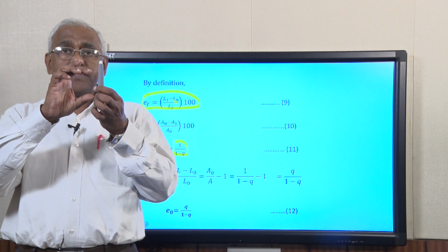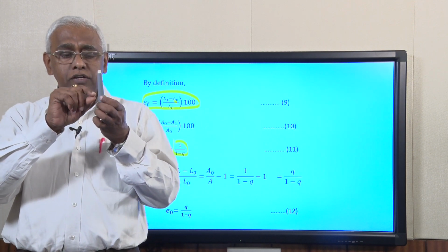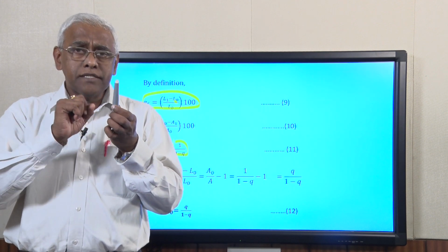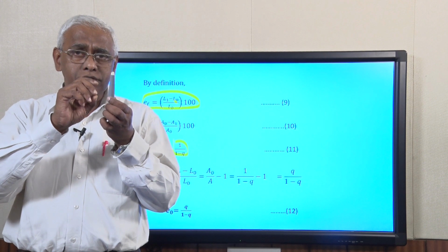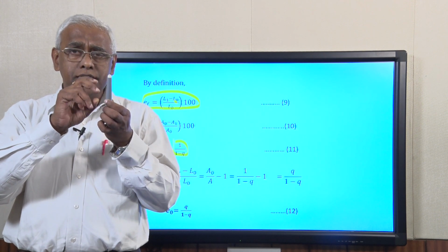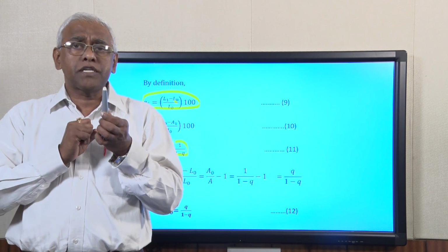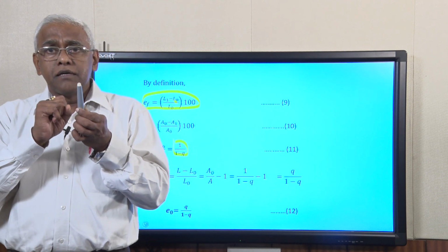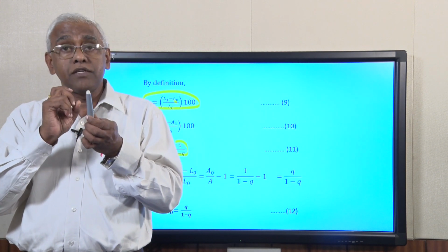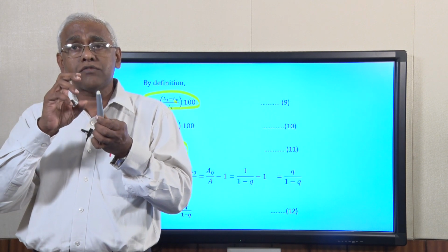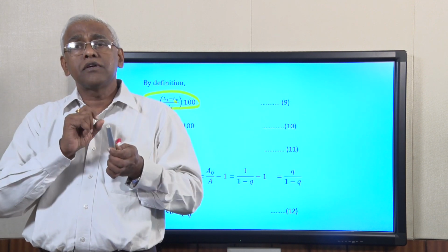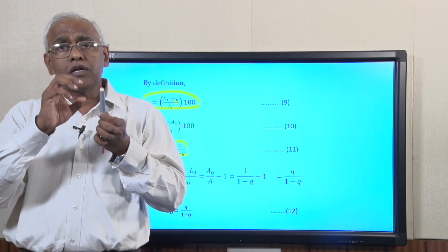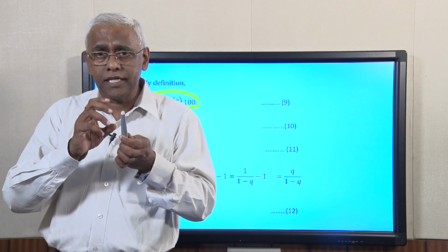Okay. So, when you are keeping a 2 inch specimen gauge length, failure will be taking place, necking will be at some small area only. If it is a 1 inch gauge length, then you will find the total length is reduced. So, if you are taking a 12 inch gauge length section, then you get much better accuracy. But depending upon the gauge length, your strain value may be different. So, you have to always specify what the percentage elongation was across the gauge length, maybe 25 mm or 1 inch or half inch or 2 inches.